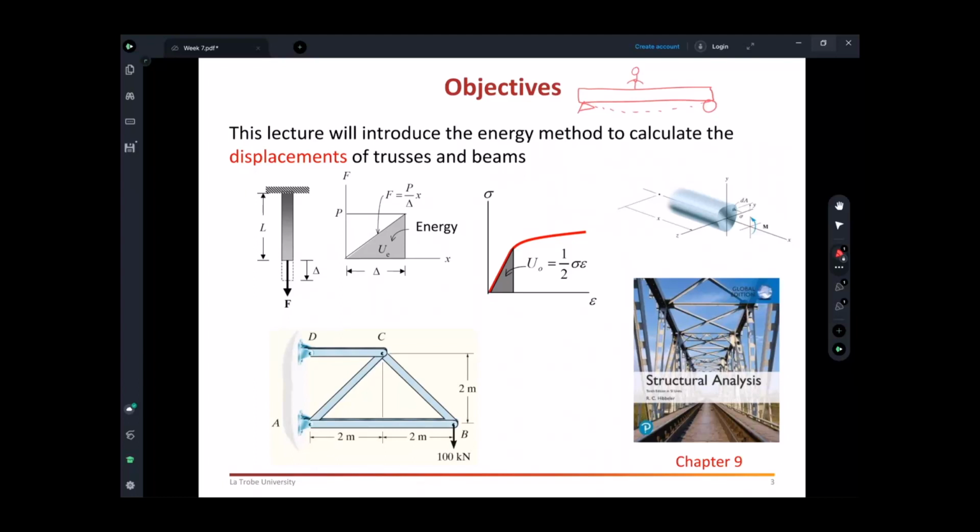The word serviceability is used in design. Serviceability means that your structure should be serviceable. You can design the structure to be safe, meaning that if the users are using your structures, beams, slabs, it is safe and not failing. But if it is deflecting too much or vibrating too much, the users of that building are not able to use that service, because it's not serviceable. So we need to make sure that the structures are safe and serviceable.